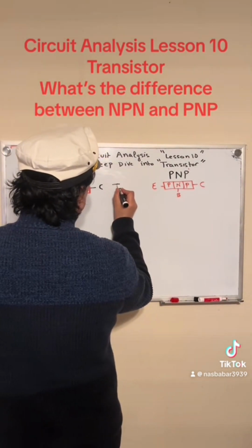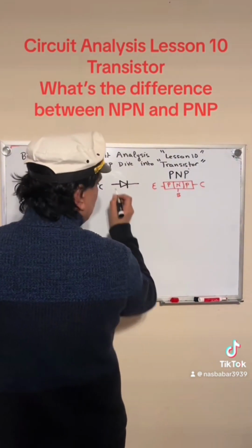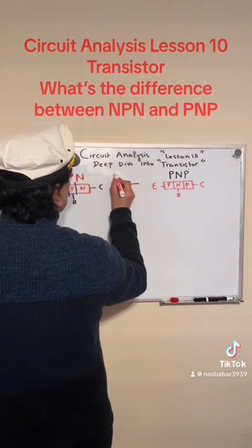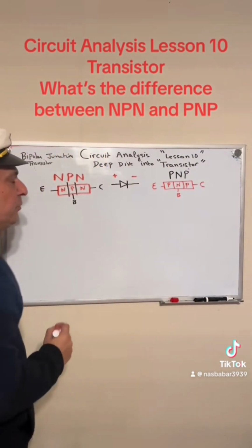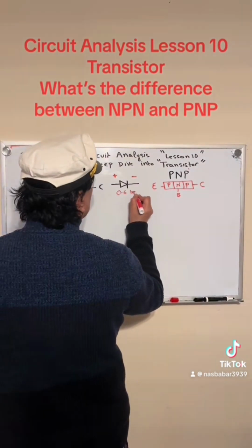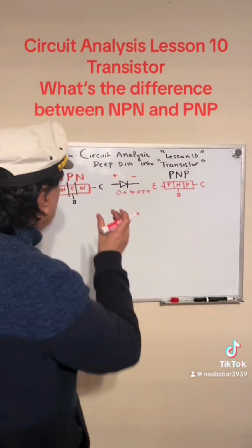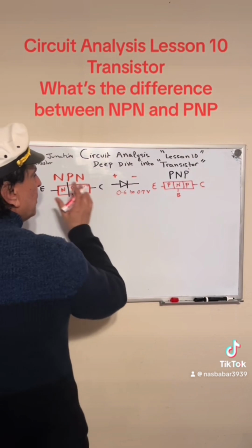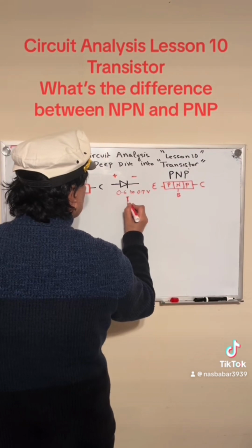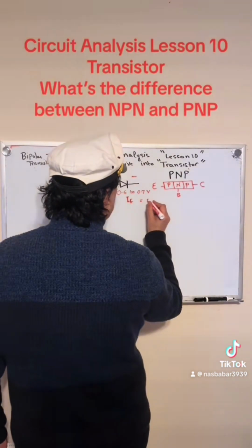If you look at the diode, this is the symbol of a diode right here. Okay. And you have current flowing from right to left. You have plus and you have minus, okay? When the voltage is around 0.6 to 0.7 volts in a semiconductor diode, you will have current flowing in the forward direction. So I of F will be present, and what that means is that your diode is active. Okay.